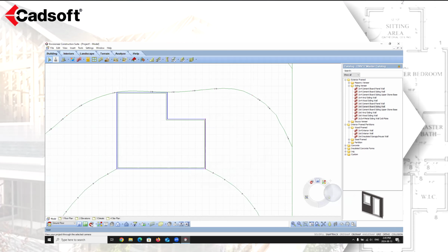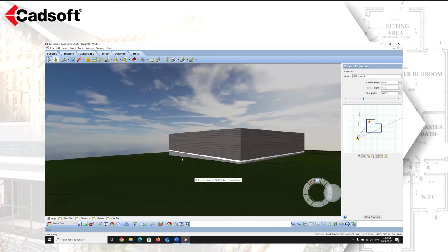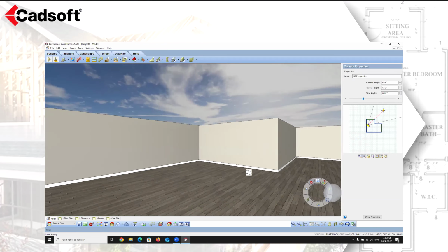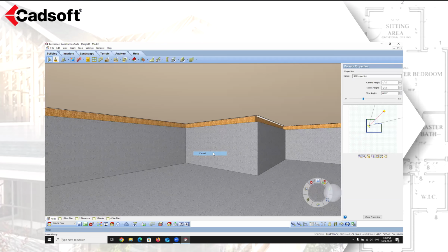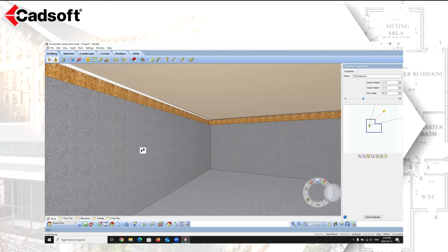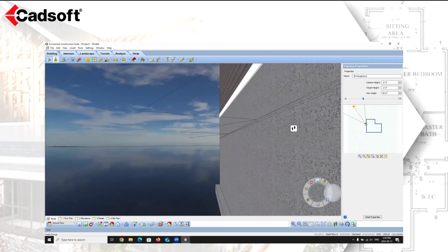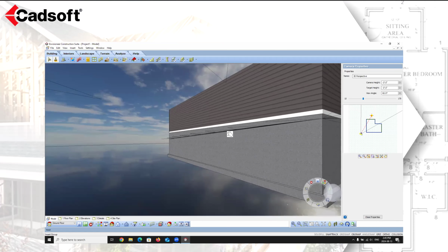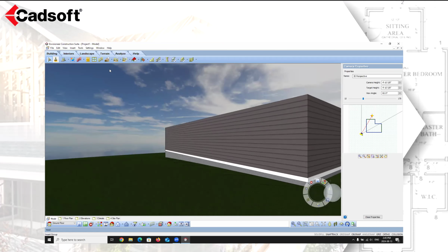And so now what's going to happen is we're going to see the foundation wall. We're going to see the terrain up against that foundation wall. And when I come into my actual basement, we will see that it's cut the terrain away from the foundation. So that is a different way of adding in your sloping site by using your spot points.